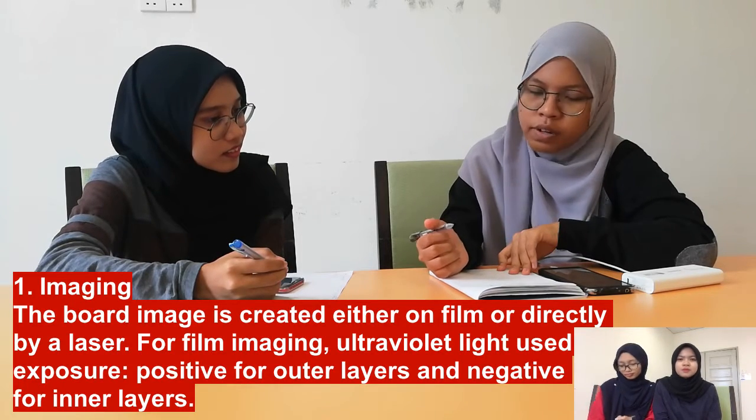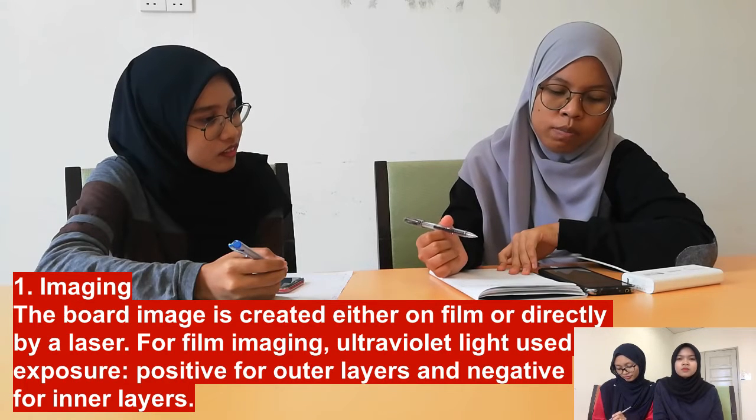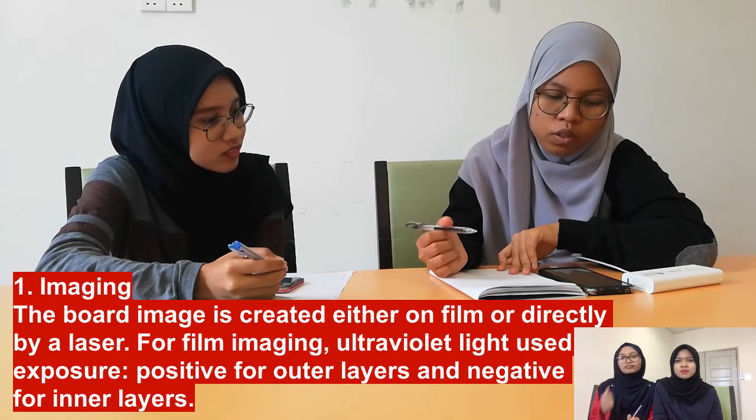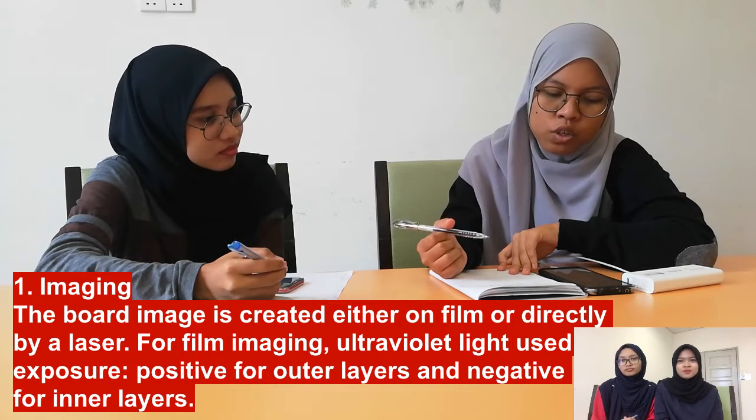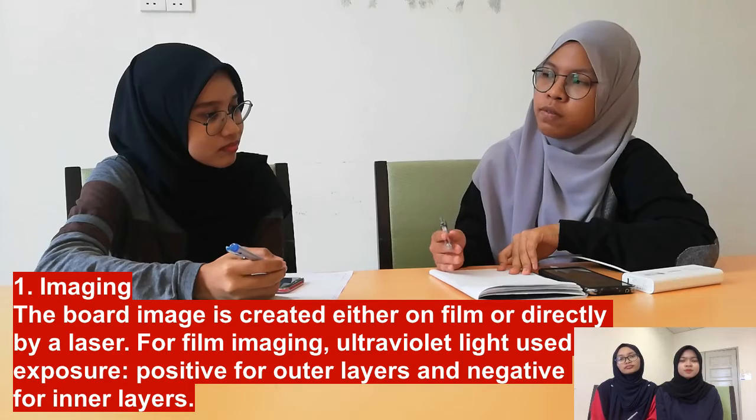In order of operation, the fabrication steps are: the first step is imaging. During this initial step, the board image is created on film directly on the board by the laser. For film imaging, UV light is used for exposure, positive for the outer layer and negative for the inner layer.